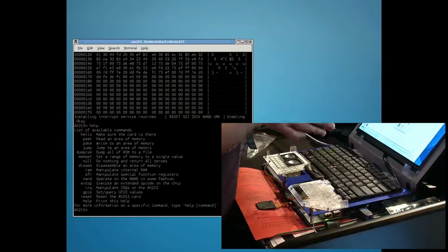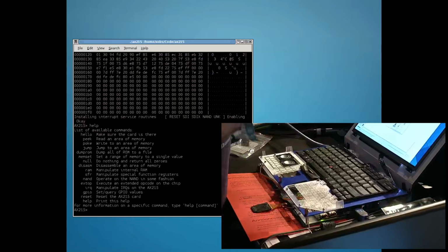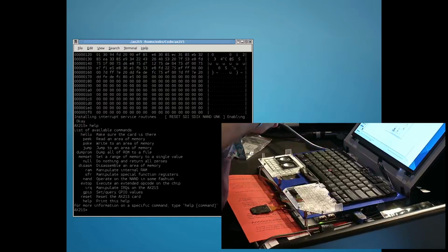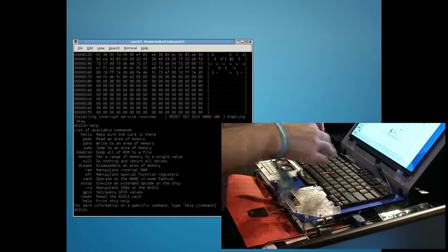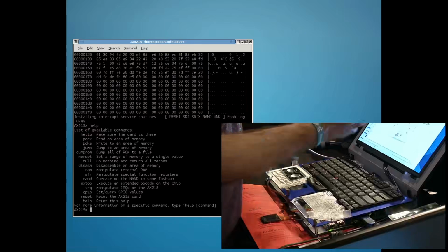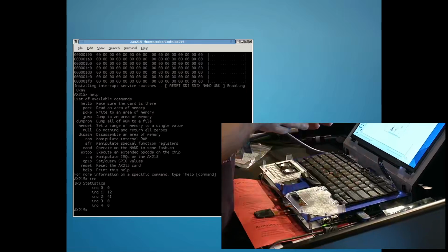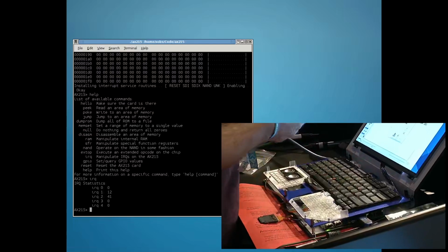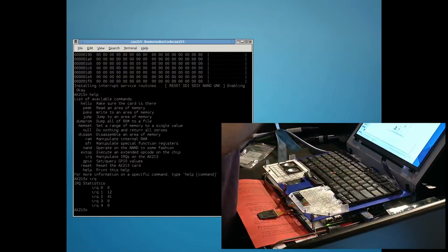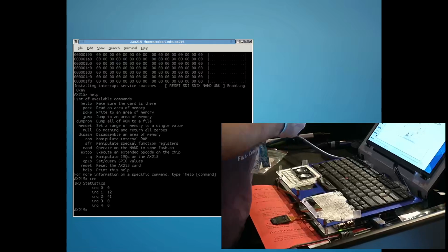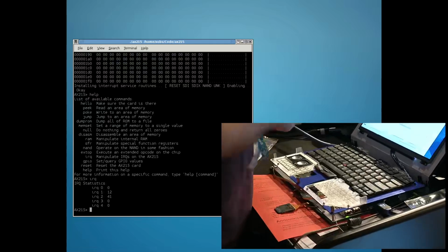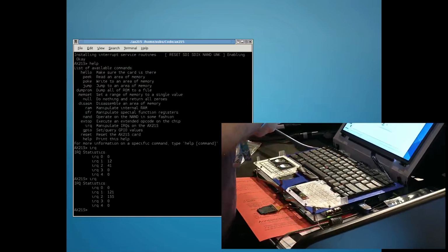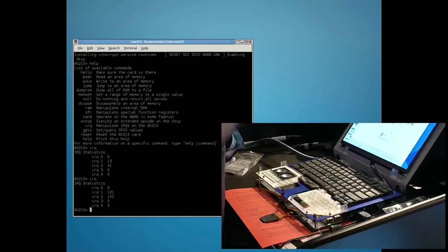So we've got a few commands you could run. There's hello, peek, poke, the usual ones. Jump, so you can load code in with peek or with poke and actually jump to it. There's the IRQ command, which is what we use to figure out what the IRQ table does. This card has 5 IRQs, 0 through 4. IRQ 0 we know just from 8051 is reset. If you look at this, IRQs 1 and 2 are not 0. And if we query the IRQs again, they keep going up. These are counters for the number of times the IRQs fire, just to clarify.